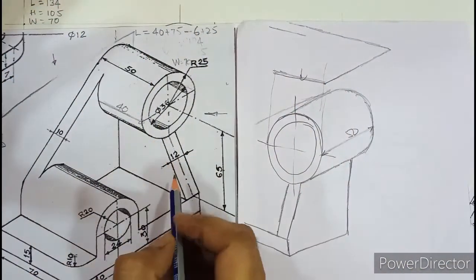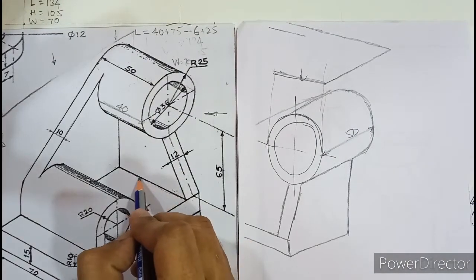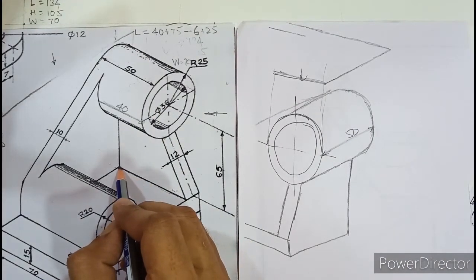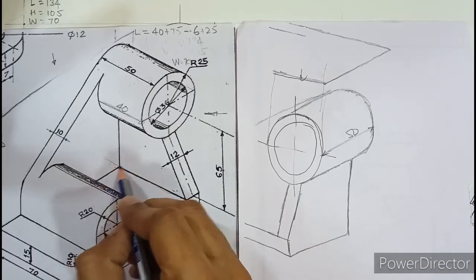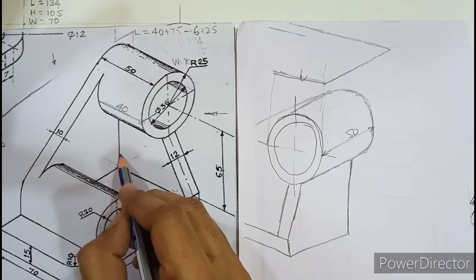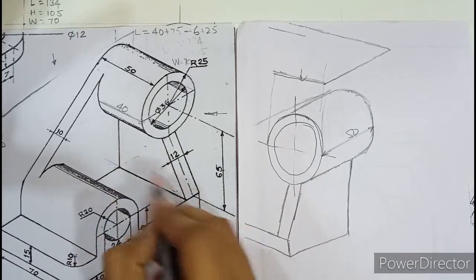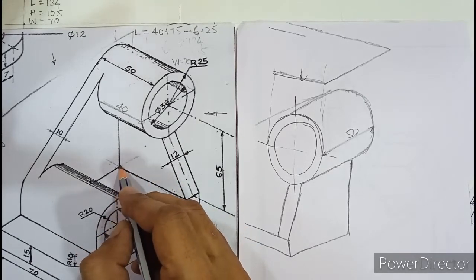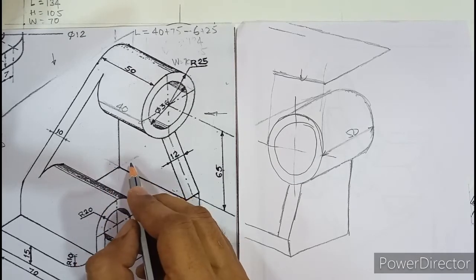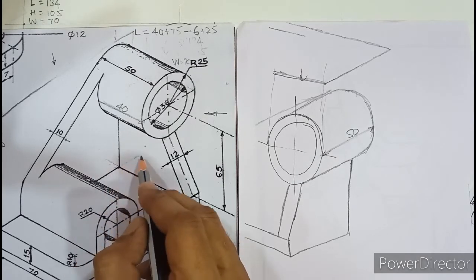It means if you look at this edge, it is only till here. You should not assume that this edge is penetrating inside, nor this edge is penetrating down. The edge is present only till where you can see. So it is assumed that all objects in orthographic are made up of one single piece of block.